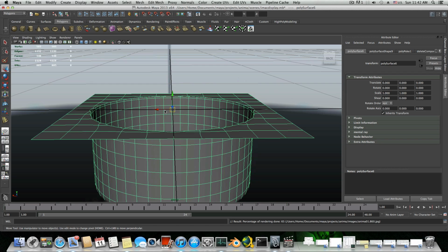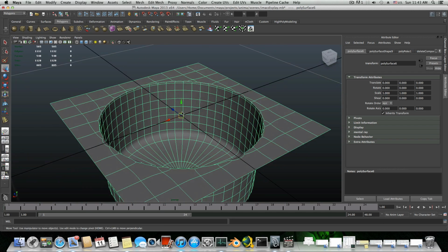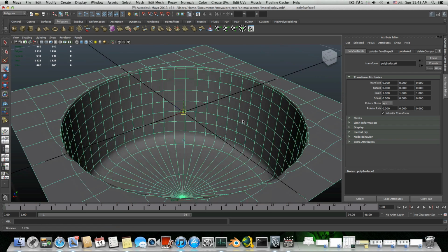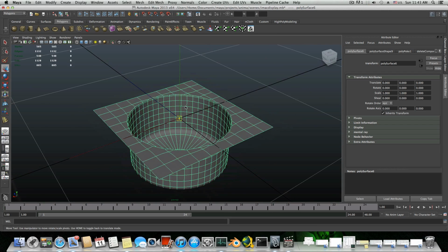That means if you're using Windows, click on the insert button. It's somewhere around the enter button, to the right of it. You have an insert button, and it will change your move tool gizmo to something without arrows. So I will show you. Now it looks like it has no arrows. If you want to make it bigger so you can see it better, you can just tap on the plus, or minus if you want to make it smaller.